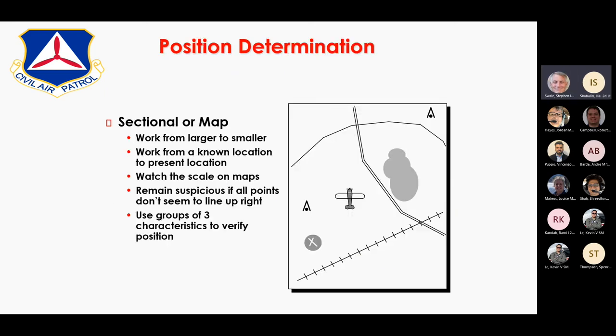Position determination is a synthesis of all kinds of inputs into your imagination. I have talked to people that have begun their training with GPS. Somebody even wrote a book called Children of the Magenta Line, I believe. And I've talked about people that think in different ways about navigation. One orientation that is really important in a G1000 airplane during your setup is to decide whether you're going to orient the map north up, which is my preference, or if you're going to orient the map track up.